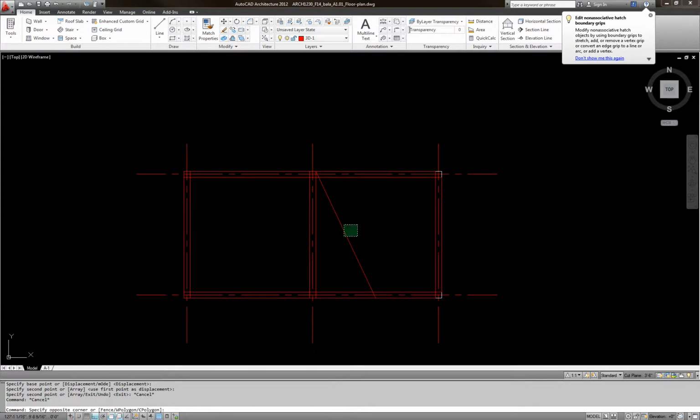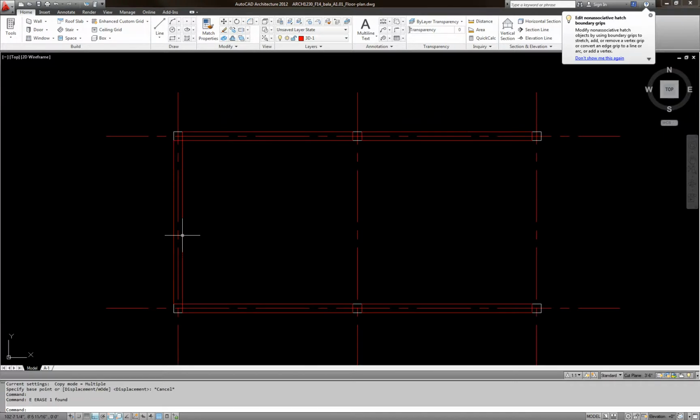If you're using a one-way slab, one-way joist slab, which we're using, you will have to copy this. I'm going to copy this joist here. So this is going to be my joist, and I don't need this here, so that's my beams running through here.